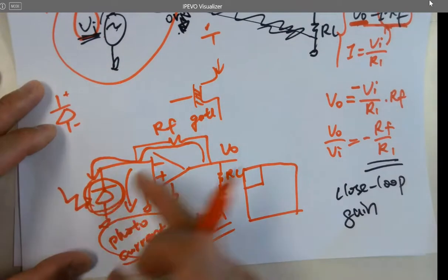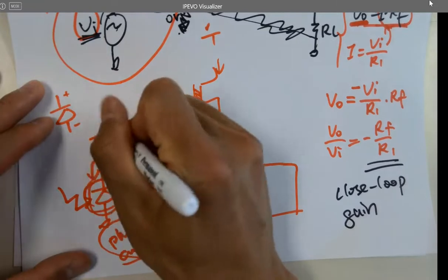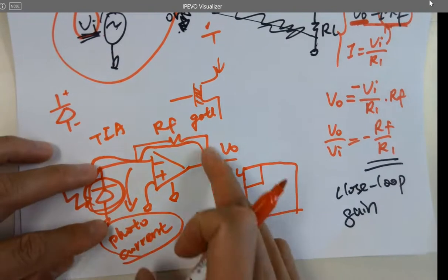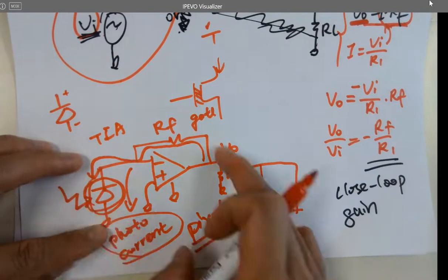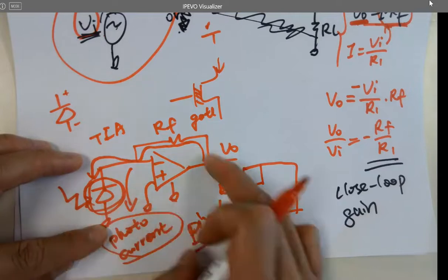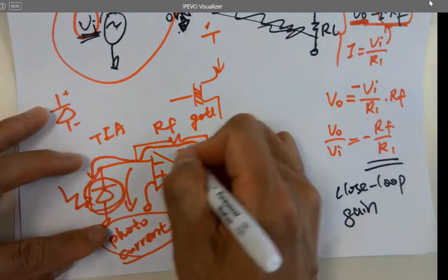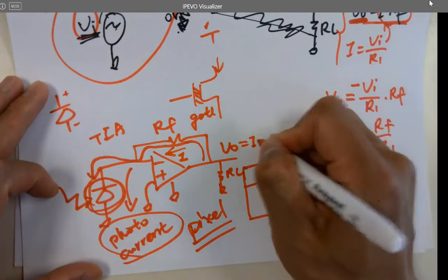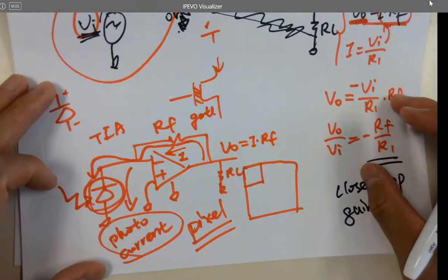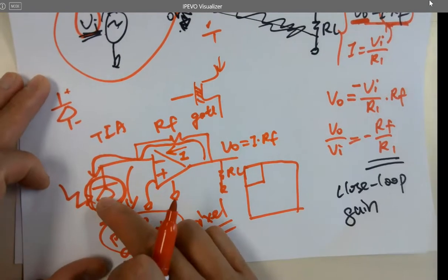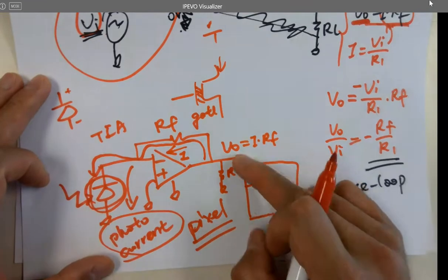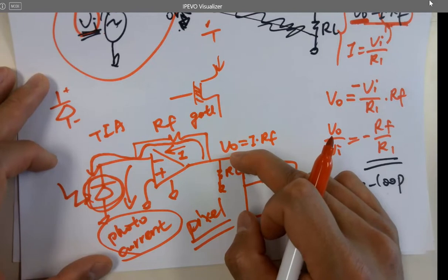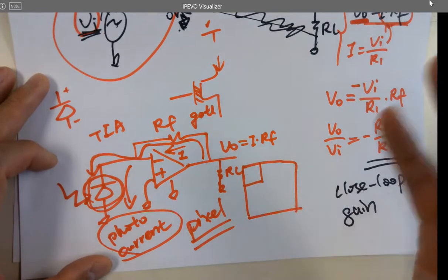So whenever you put this one in the TIA, whenever it generates charges, it's going to pull photocurrent over here, and what's going to happen? You get a voltage signal. Depending on the number of photons being received by the photodiode, you are going to have a different voltage level here. And you can convert the voltage level into the intensity of the pixel, right?